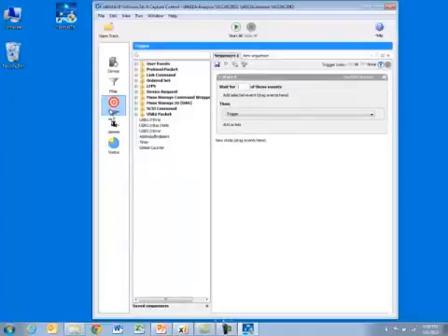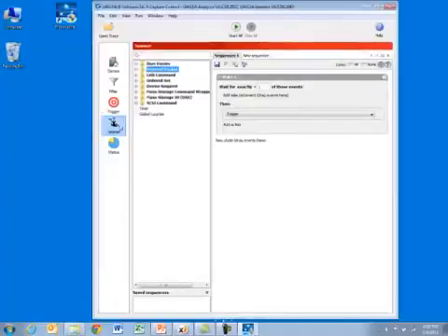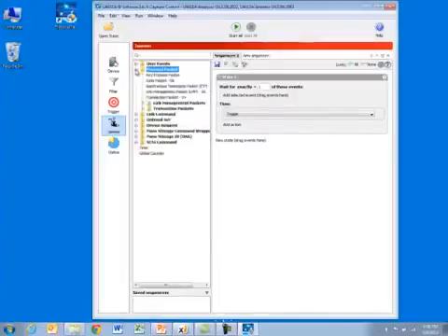Right now, I'm not using the trigger conditions of the analyzer at all. If you want to know more about the trigger conditions, please see the companion video on the U4611A protocol analyzer. But what we are interested in is the jammer capability. The jammer has a programming language that uses the same interface that we use on the analyzer to look for specific commands. What do you want to do in an operation? Looking for data packets or timestamps or mass storage commands, and then operates upon those.